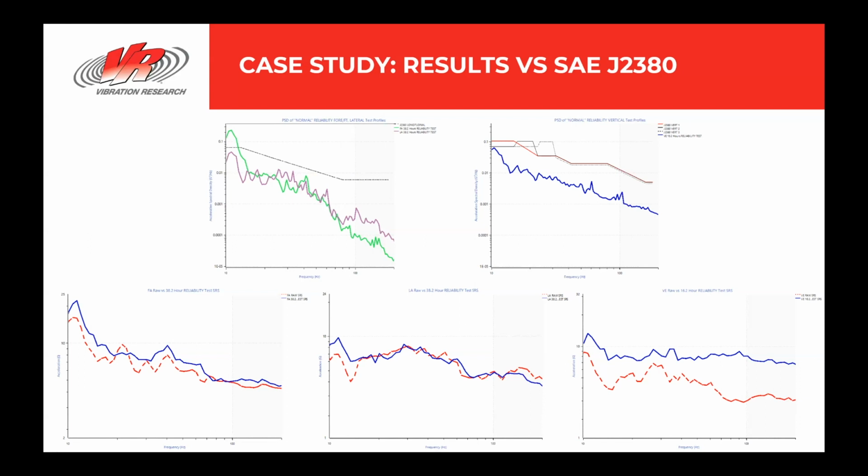The fatigue damage spectrum provides a clear path for doing this. You can measure vibration on internal battery components to improve robust design and/or find cost savings. And you can use that data to generate profiles to run specific component tests without having to have the entire battery pack to do it. You can use these results to improve your supply chain quality, reliability, and durability.